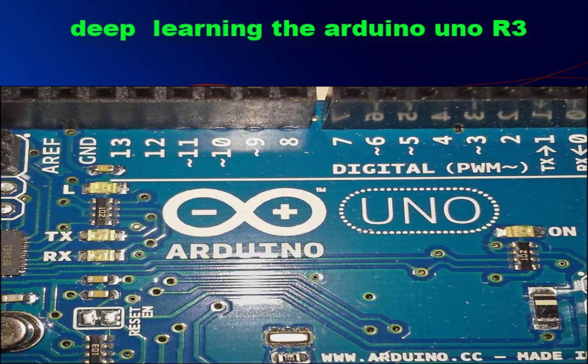The Arduino Uno also has 4 built-in LEDs. A green LED, marked ON, that indicates when the Arduino is receiving power. Two yellow LEDs, marked TX and RX, that indicate when the UART serial interface is receiving or sending data. A yellow LED, marked L, connected to digital output socket 13 that you can control from your programs.